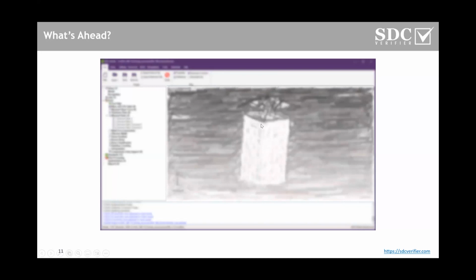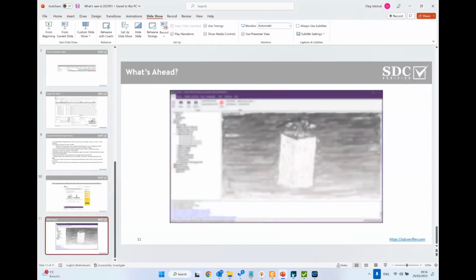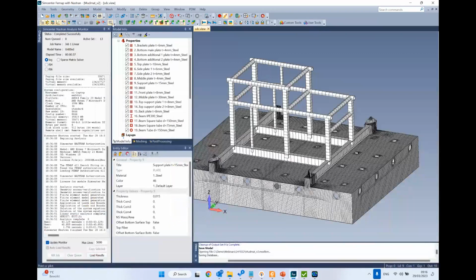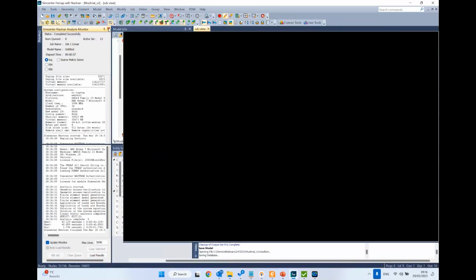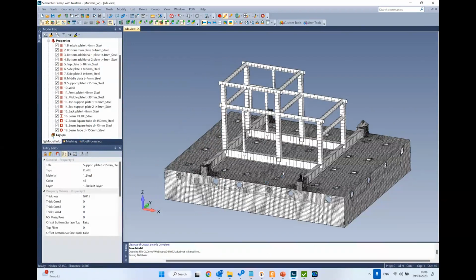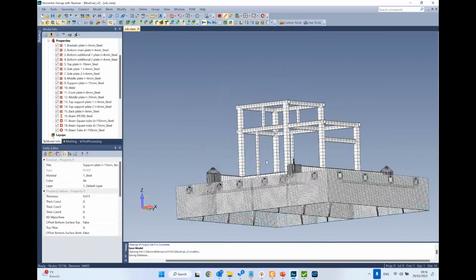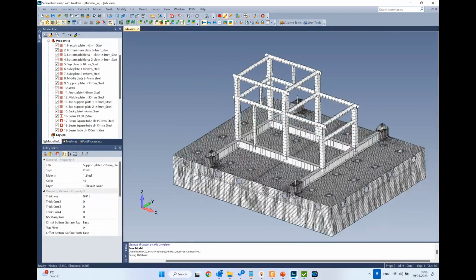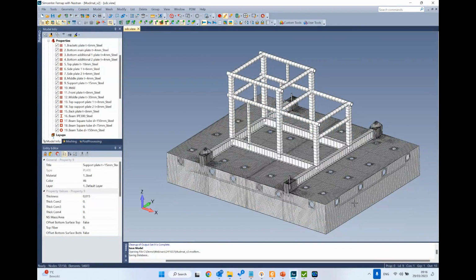Now let's go to the demonstration of this new interface. I'm going to demonstrate that today on a FEMAP model. As already mentioned, it is completely the same for ANSYS or SimCenter or our independent product in the future. This is a very nice model because it has different types of elements: connections, joints, welds, plate fields, beam members.